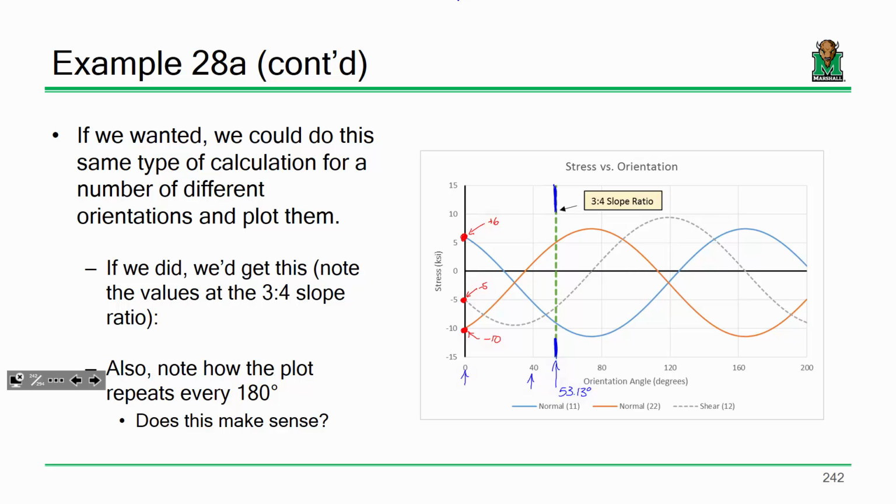And what are the new values that we're getting at this location? Well, we're getting a sigma sub 1, that's about right there. What'd that come out to be? About negative 9.04. What did sigma sub 2 come out to be? Came out right about there. What was that? 5.04. What about that shear stress? About right there, negative 6.28. Kind of crazy, isn't it, right?